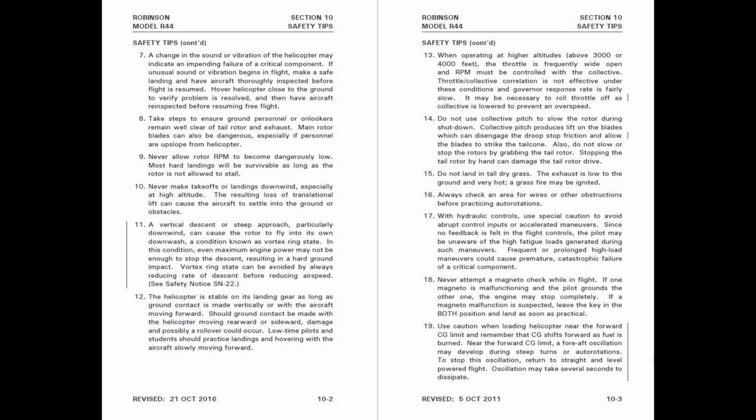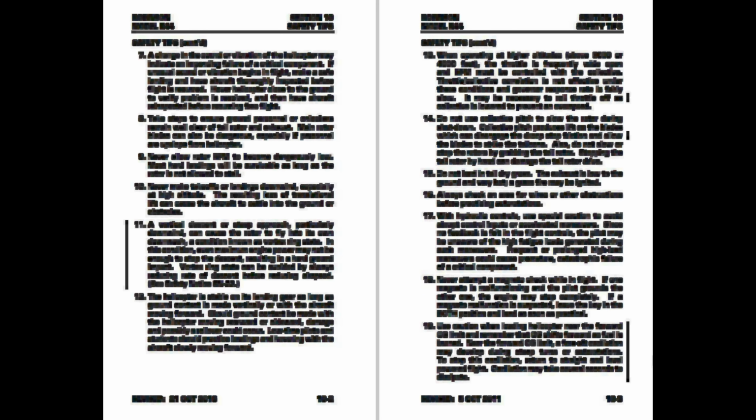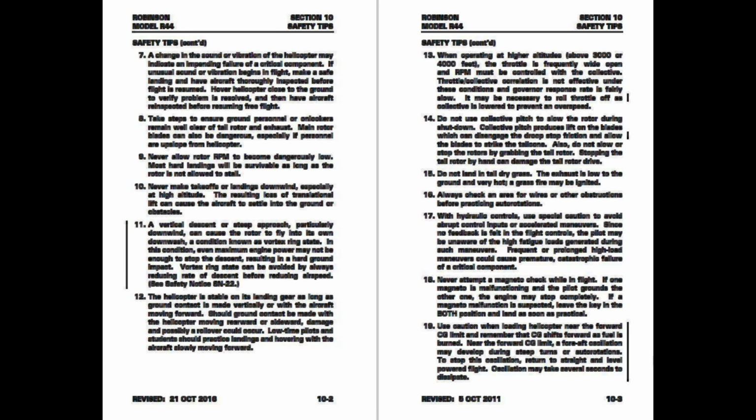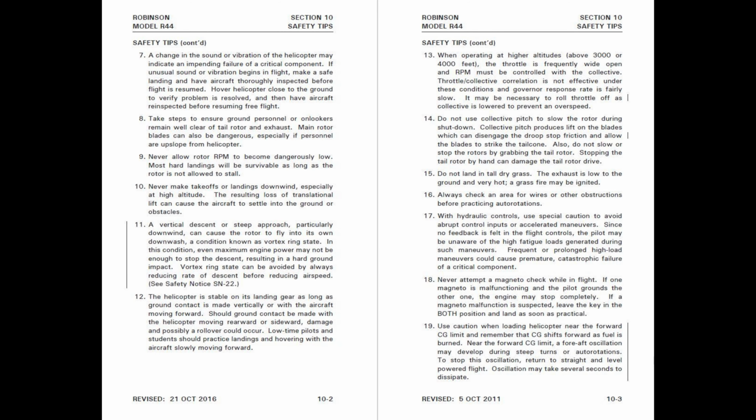The center of gravity has shifted forward. How does a pilot stop that oscillation? Return to straight and level powered flight. It may take a few seconds for the oscillation to dissipate.